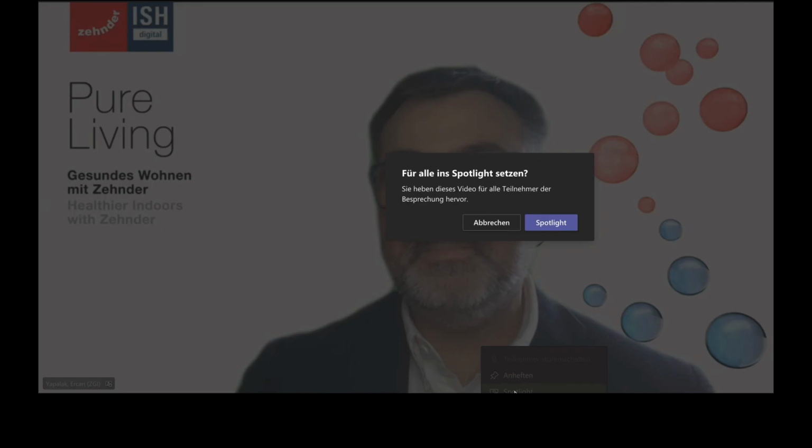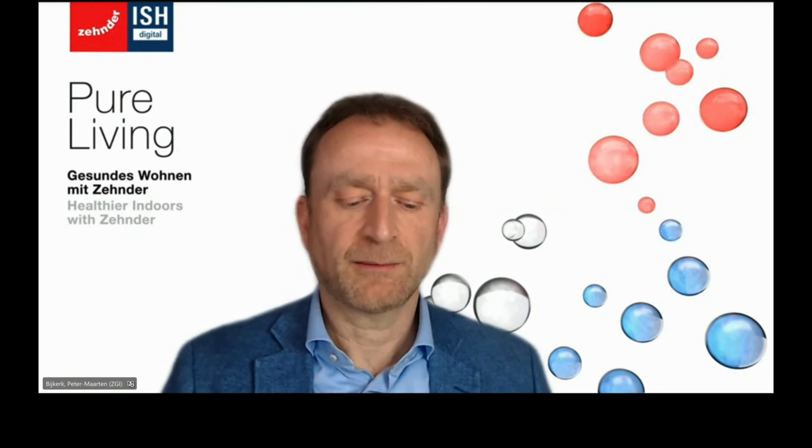So the KNX question I would like to give to you, Peter-Maarten. I hope I could answer it, Thomas. Otherwise, don't hesitate to get in touch with me. Great. For the KNX, the answer is that for the REST API, you need the ComfoConnect LAN-C and the IoT cloud. That's the base for it. So if you have a KNX installation, you would need another gateway to do it. But things could be complicated because if KNX is connected, the KNX system rules. So the KNX system really determines what the ventilation is doing. And you could use the REST API to read out the data mainly. That's the key use case if you combine it with KNX.